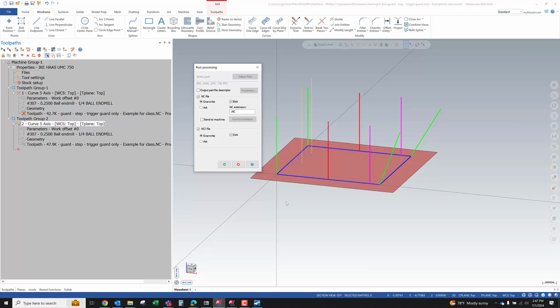we want to verify that those jaw faces are parallel at 0 to the B-axis, because even if the table is zeroed, if the stack up of our work holding is not precisely zeroed, we may need to re-zero the tool change offset on the B-axis to ensure it's perfectly parallel, right? So that everything works. And that's really the goal, right? Is, hey, I want to make 5-axis easy. Well, that requires that we make sure that our setup is correct before we start.